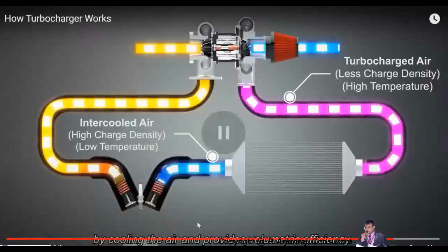So here you see it is very much important. You have the difference between the intercooled air and the turbocharged air. When you go for turbocharged air, you have high temperature and less charge density. And when you go for the intercooler, you increase the charge density and the temperature gets reduced.